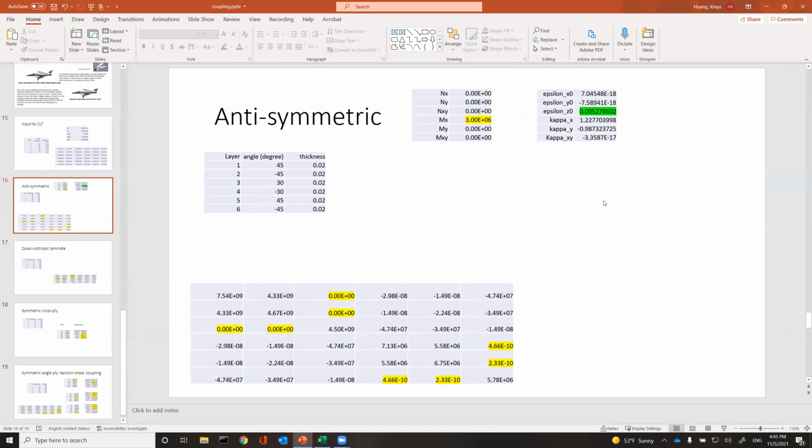All right. The other interesting thing is I have no twist. I put a pure bending on it. See, I have a curvature in both directions. It's saddle shaped. Look at the deforming saddle shaped plate, but no twist. Look at the twist. Twist 0. No twist. So there's no bending twist coupling here. That's due to the fact that these two terms are 0.